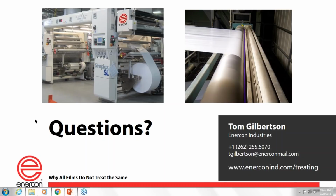If the electrode is canted or off adjustment in some way, to where the corona can be closer in one area than in another, the corona is always going to go to the path of least electrical resistance. In that example, you're going to get more energy on one side of the web than on the other. And when you do a dyne test, you might find that the dyne level is higher on one end than on the other, and that's not really attributable to the material composition. It's attributable to the mechanical setup of the corona treater typically.